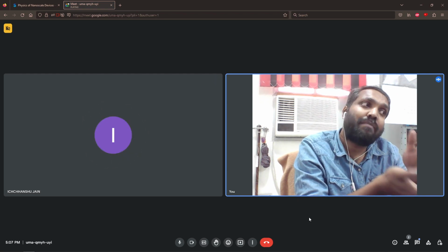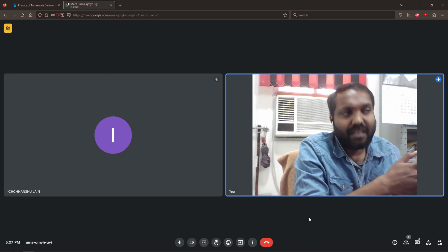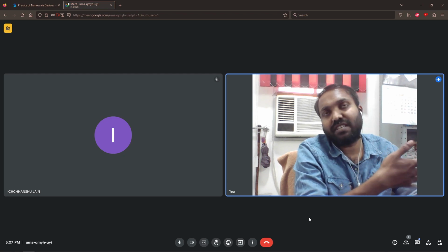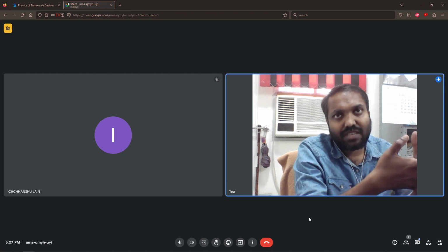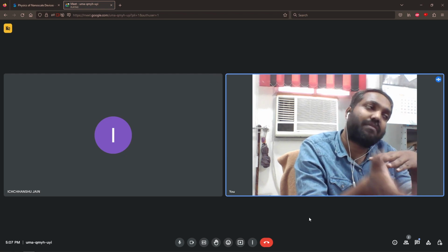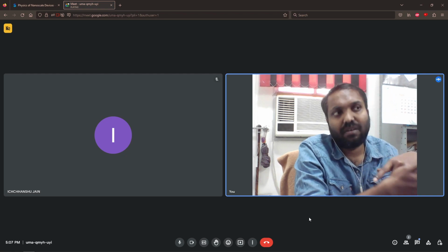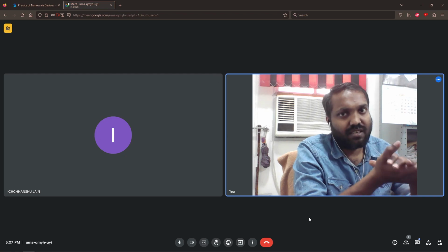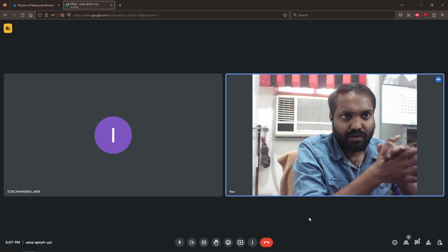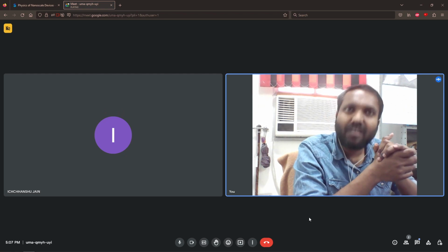Yes, sir. That essentially places a constraint on how fast the electron can move through the channel. So ultimately, that will lead to what is known as velocity saturation. And since charge times the velocity is the current, that will also give us a current saturation. And this saturation is what we observe as the switching from the linear regime to the saturation regime of the MOSFET. So that summarizes the concepts that we have discussed in today's session, and this should help you by and large to solve the assignment questions.